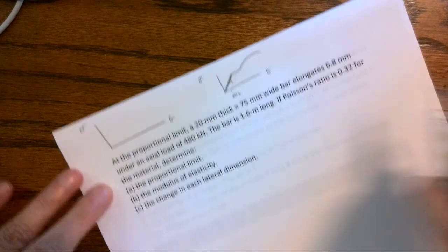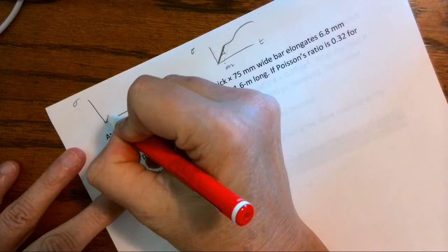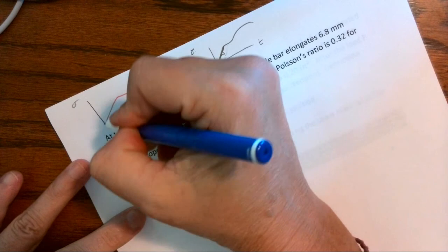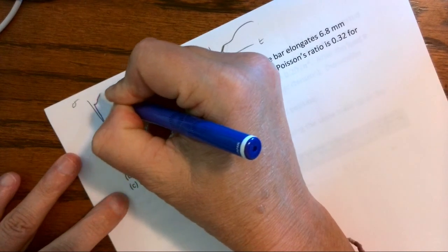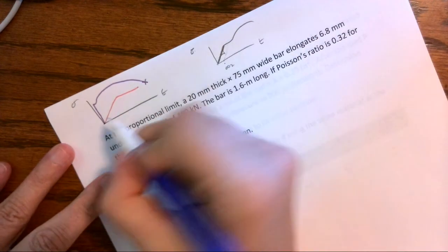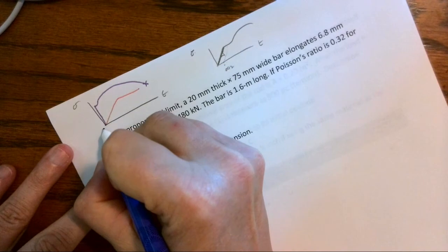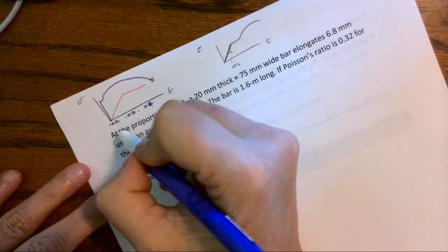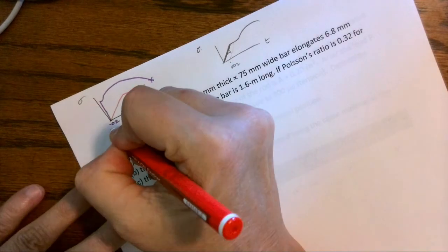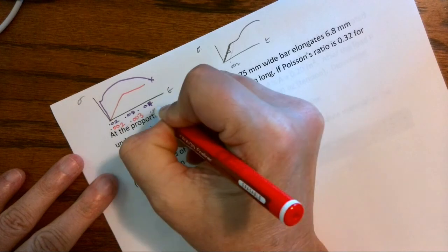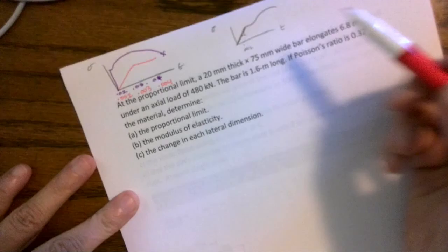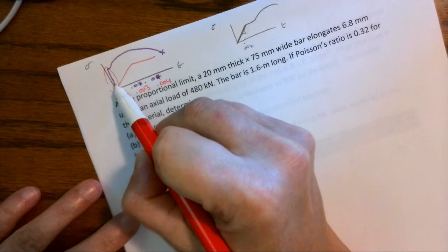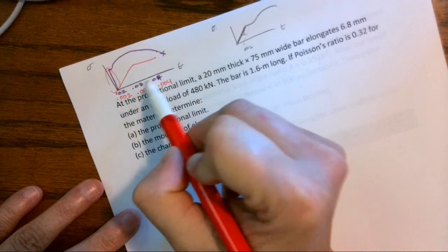Okay. A quick side note, the question today in class: if I have a stress strain curve and I have two graphs, one looks something like that. This is so we can get a very good bird's eye view of our elastic region. The other one is more like this, and then it just kind of goes over. So if you're looking at it, it's two different colors. You're going to have values of strain, and maybe they're very large up here on the top. And then on the bottom, it's very similar values, except we are at 0.002, 0.003, but you can see it's a different scale. It's because the strains in the elastic region are so very small before yielding takes place, we could never use the purple scale to figure out what those strains were.